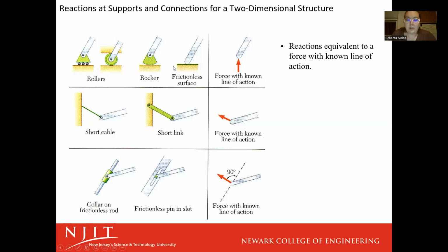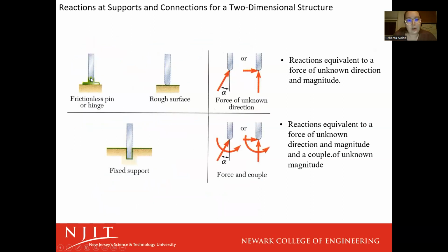But the first row, let's think about if you had something on rollers, how is that roller going to constrain motion? So we want to introduce forces in the ways that the reaction joint constrains motion. So rollers are able to move left and right. You can see that there's a pin here. I probably should have started with the pin joint. Pin joint, picture this as welded or fixed to the ground, welded, bolted, something like that. There's this linkage that has a pin going through it that also goes through what is stabilizing it to the ground. So that's going to prevent it.